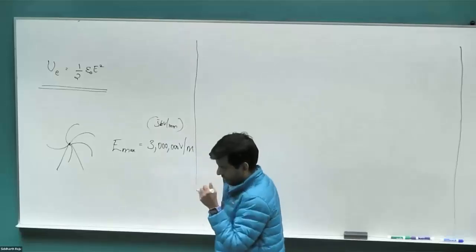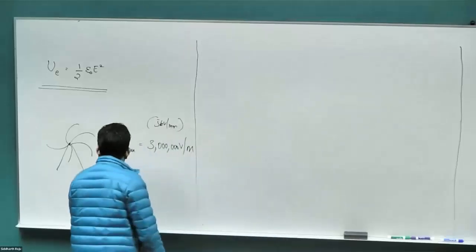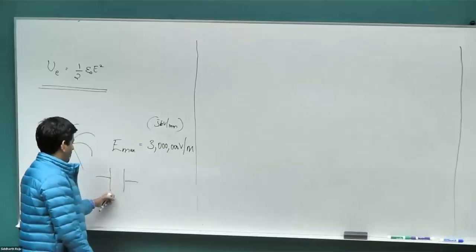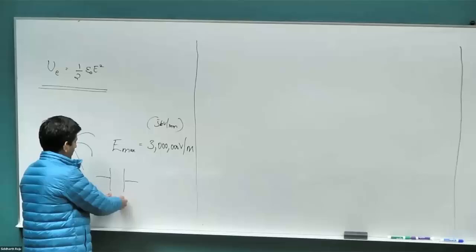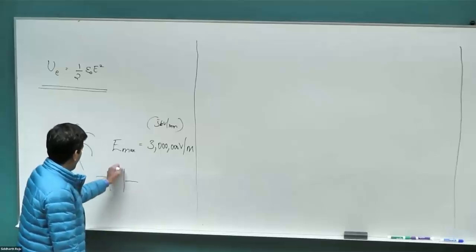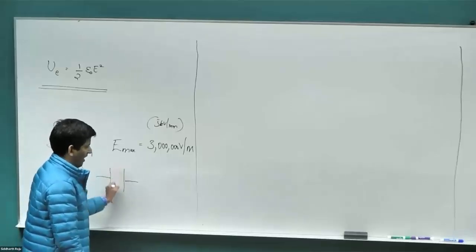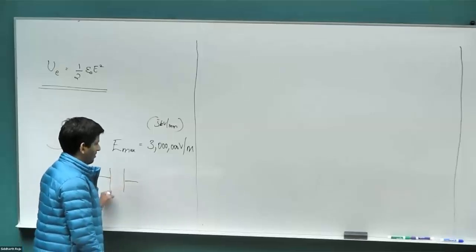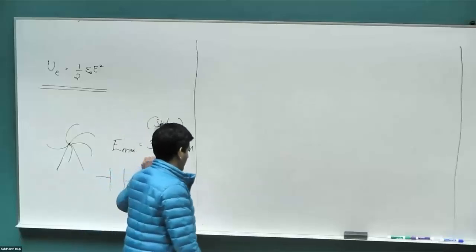Right, so above this, if we have 2 parallel plates of some mechanism, and then we put a voltage large enough such that if you divide the voltage by the separation of this plane, and all that is separating these two is pure air, nothing else, then we would end up having corona discharge. So we want to avoid it, but push it up to that point.